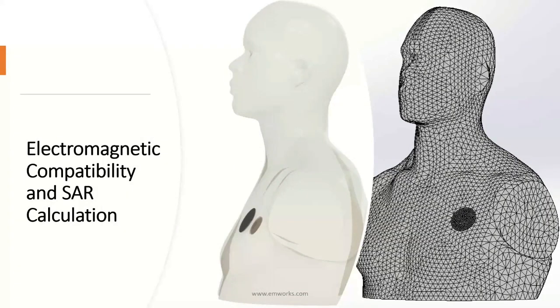Now we're going to have an idea about electromagnetic compatibility and specific absorption rate. For implanted and wearable medical devices like pacemakers, and also wearable devices like phones, the electromagnetic radiation should be limited as much as possible and not exceed the EMC standard limits established by international healthcare organizations. Therefore, we have simulated the wireless charger system in realistic conditions. We have used a human body where we have put the receiver. Both the transmitter and the receiver operate at resonance to have maximum transferred power.